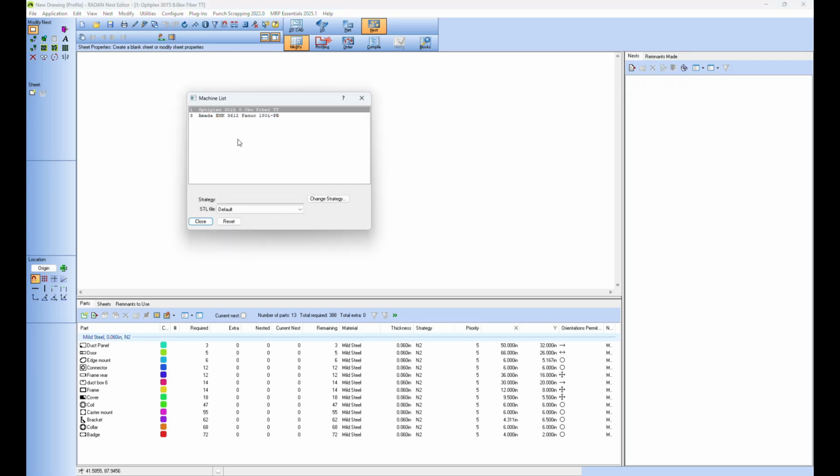now, we used to only have just a single laser, and now we have a punch, which are extremely different pieces of equipment. A laser has great maneuverability. It can get into tight places. It has a very small cutting path, whereas a punch is a bit more restrictive. It's dependent upon what the machine capacity can do, versus if it has lots of auto index stations or very few. And then also the tools are much larger than a laser beam. So we can't necessarily start all the time just with a singular template.